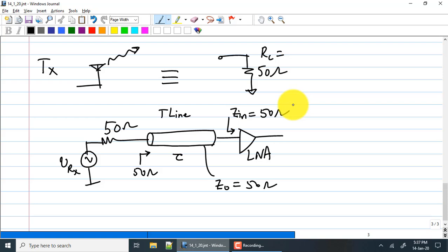If that happens, there are several unwanted scenarios. For example, you might have a nearby reflector which could cause the signal to get reflected and come back again, which could then add destructively with your original received signal. You could get multiple copies by a certain time. That is also possible, so you normally don't want that.